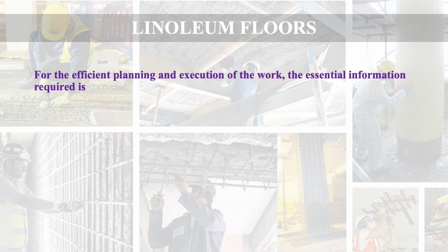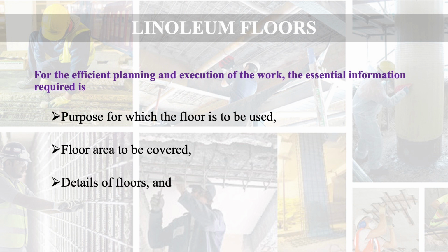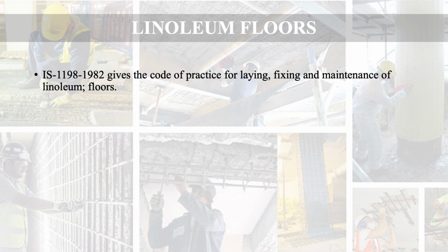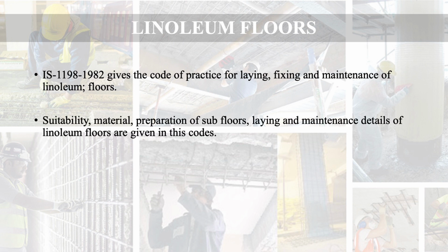For the efficient planning and execution of the work, the essential information required is, first, the purpose for which the floor is to be used. Second, the floor area to be covered. Then details of the floor, and finally the type of soil in the sub-base and any seepage problem, etc. IS 1198:1982 gives the code of practice for laying, fixing and maintenance of linoleum floors. Suitability, material, preparation of subfloors, laying, maintenance, details of linoleum floors are given in this code.